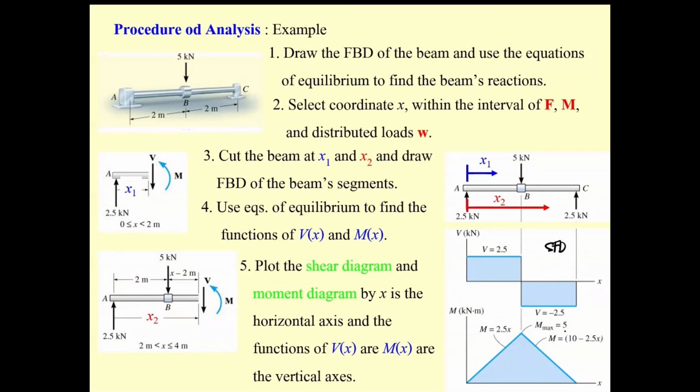And then we write the equation again and now we know the bending moment diagram. And now I can say something. w here is 0, so the shear here is going to be constant, and the moment is going to be a linear equation.